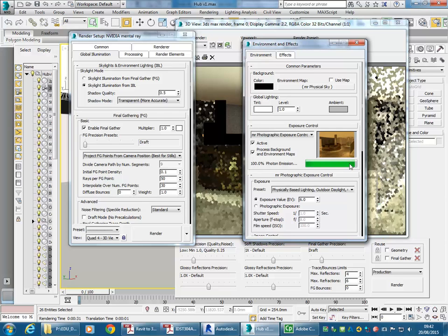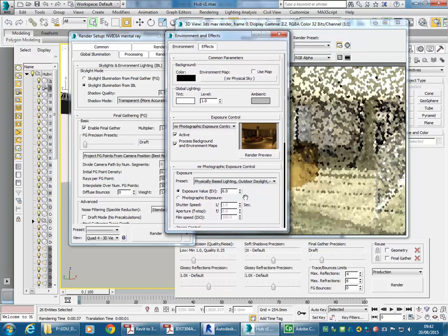It's usually just when you're using the sun that you need to have this multiplier adjusted. Without the sunlight, the artificial light will give enough distributed light so that we don't need that extra final gather. So it should be a bit darker on the ceiling especially, and there we go. You can see the difference really clearly there. I might just go down a bit lower to an exposure value of 5. Okay, so that's done, and that's set up for nighttime render now.